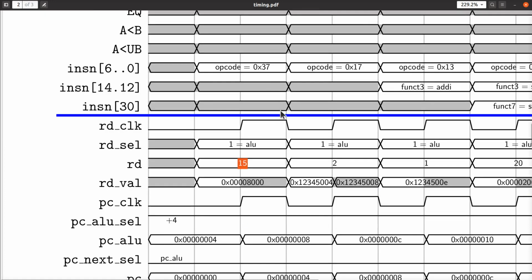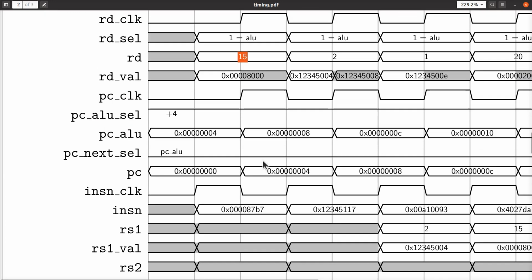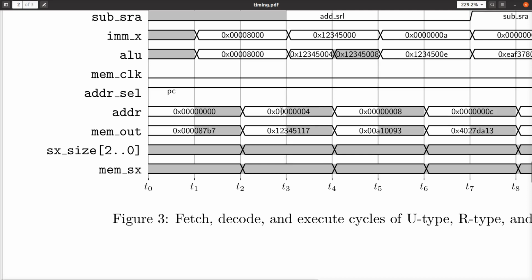The latter half of this instruction cycle, as I mentioned before, is dedicated to dealing with advancing the program counter. Because remember, in the RISC-V, we advance the program counter at the end of the instruction. That has to happen somewhere, and it takes a certain amount of time. So we do that in the latter half of the instruction phase, okay? You can see that we go from 0 to 4 here. And that 4, as I mentioned earlier, goes down to the address for the memory bus, and the memory output reflects the value of that new address, right?